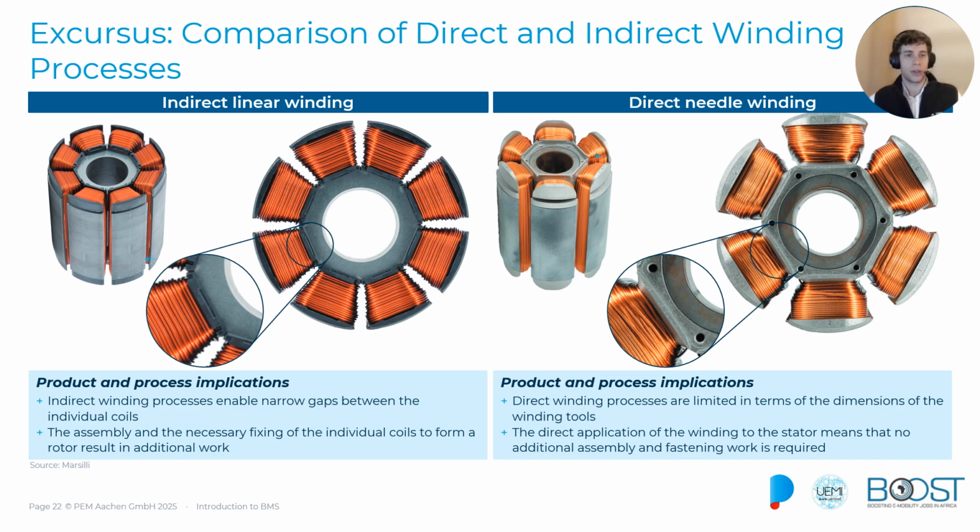Direct winding technologies like the flyer winding place wire directly on the rotor slots, forming coils in one step. It is faster and simpler as it eliminates the need of transferring coils, but may be less precise than indirect methods. Both processes aim to create effective winding for external excitation, with indirect offering precision and direct providing efficiency.